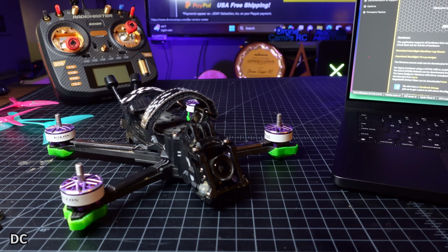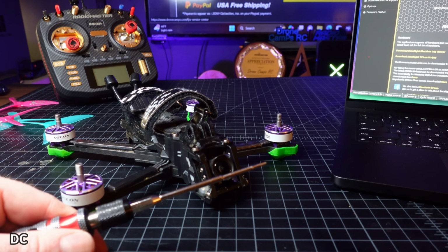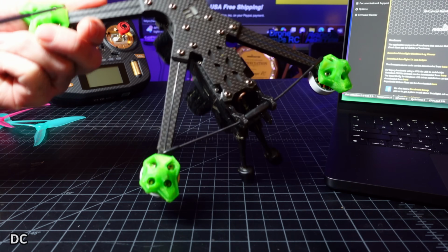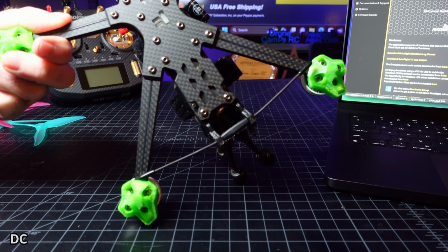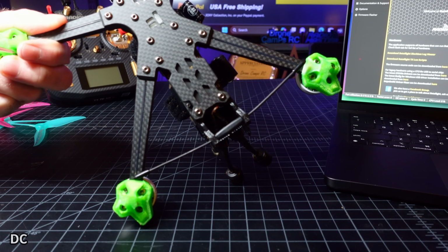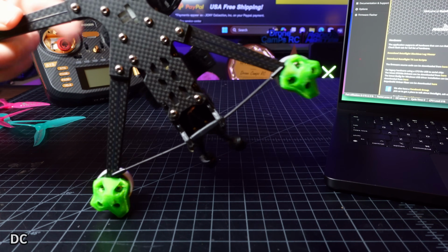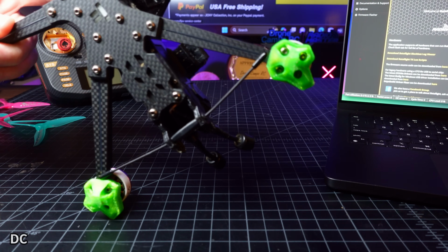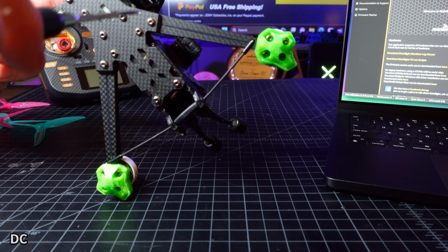Like RC helis, these quads need a little bit of physical maintenance every once in a while, and it's always a good idea, especially before your first flight, to take a driver and go around the whole quad. I always start with the motors first, and you want to give each bolt a slight turn. Make sure that everything on your brand new drone is nice and snug, and I'm talking about all of the bolts on the quad. Just thoroughly check every single bolt on the quad, and that way everything will be nice and tight.